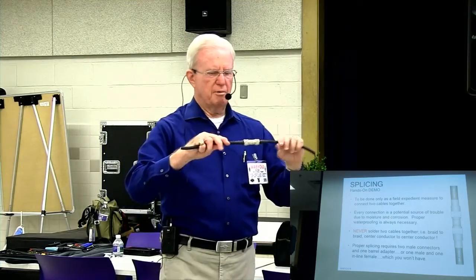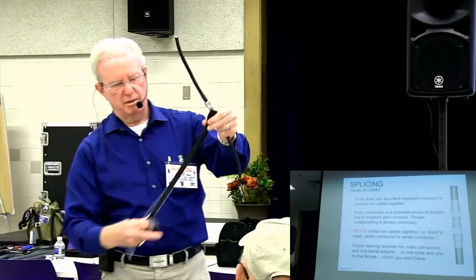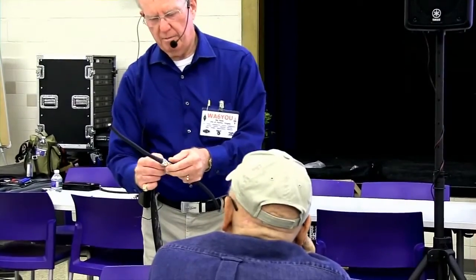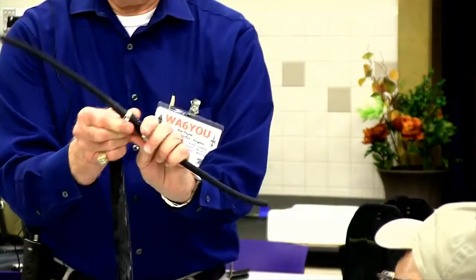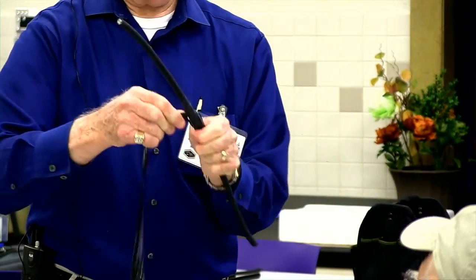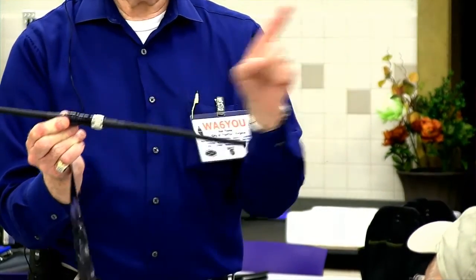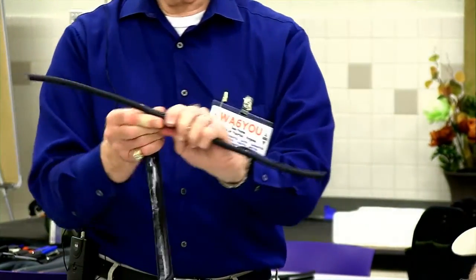And I know it only rains like once a year in Mogadishu, but here's what we're going to do, guys. Here's what we're going to do. I'm going to show you what I do. Put that there, get some scissors. And I'm going to take and wrap, and I'm stretching the heck out of this. Stretch, stretch. Did you notice the heat shrink? I didn't mention, thou shalt not put on a connector without heat shrink.